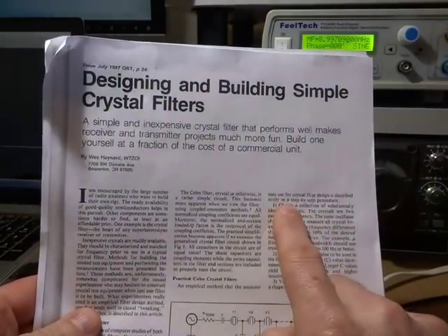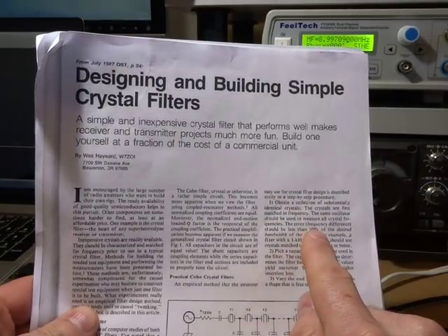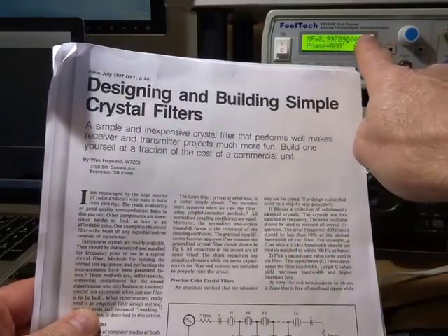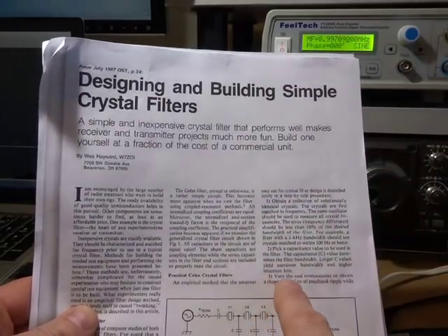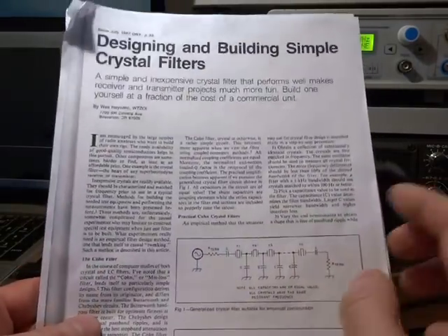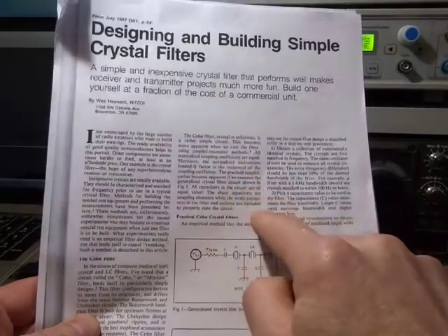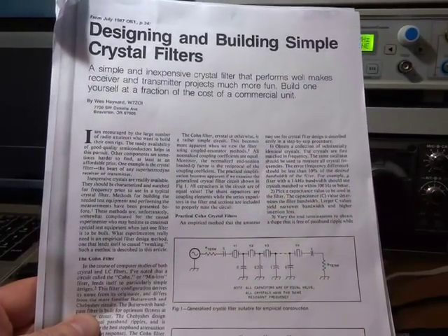So step 1 was to obtain a collection of substantially identical crystals within 10% of the bandwidth. Like I say, we're going to be considerably better than that. And then we'll come back and pick this capacitance, and then we'll do some plotting with the SIG-gen and the O-scope, and we'll plot the frequency response, and go from there.